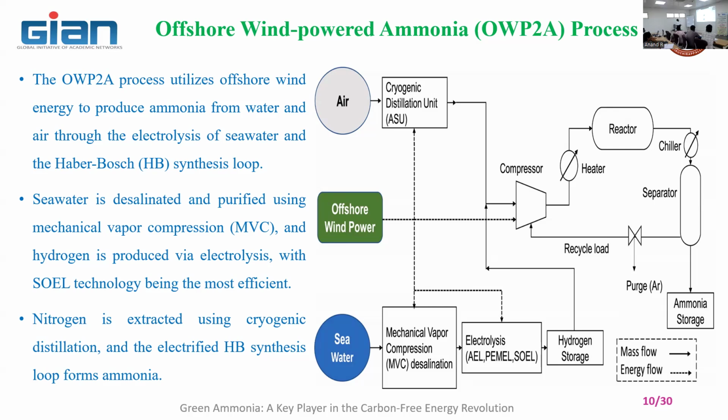Then we can go for either the PSA, pressure swing adsorption method, by providing mechanical energy to the PSA system to maintain the difference in pressure. You can separate out nitrogen and oxygen, or, the same way we discussed yesterday, separate ammonia by using a deep freezer. The oxygen and nitrogen can be separated by using a cryogenic low temperature distillation chamber, where oxygen and nitrogen each have a boiling point. So you can operate at a particular temperature and separate out the nitrogen. Then from the cryogenic distillation unit, nitrogen comes out.